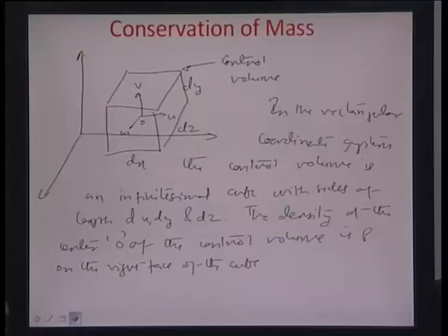Okay. And this is further like a cube around this point O with dimensions dx, dy and dz in the x, y and z directions. And what we would be looking at is that, if we assume that there is no creation of mass within this control volume, whatever is inflowing into the control volume is exactly equal to the mass that is outflowing of the control volume.